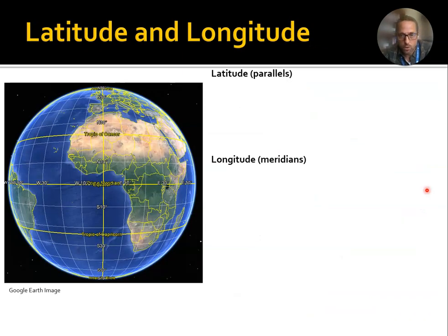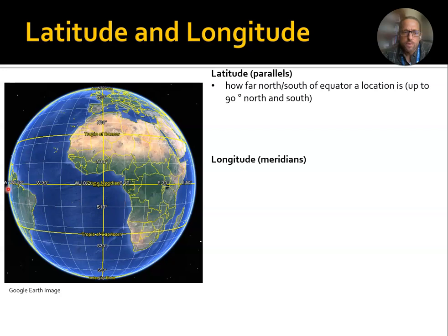But then when you get to geographic coordinate systems, which remember is where something actually exists, we're going to deal with latitude and longitude. So I want to make sure you understand latitude and longitude. The latitude is the east to west lines. So these are lines of latitude here. Line of latitude, line of latitude, line of latitude. All right, so the equator, which hopefully you're familiar with, that's a line of latitude, and that's 0 degrees. You go north, it's degrees north, right? So 10 degrees north, 20 degrees north, 30, 40, up to 90. So the North Pole is 90 degrees north. You go south, and the South Pole is 90 degrees south.